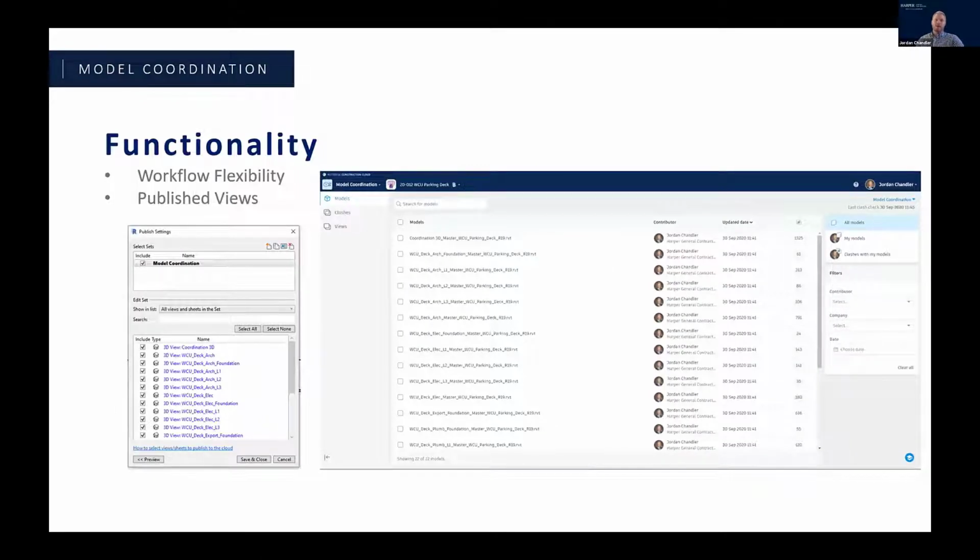Speaking to that, basically from a Revit perspective, I think a lot of coordination in some way or another comes back to Revit and some other file types. But another place where a lot of people get hung up is how do you get the data from Revit to model coordination? You can do a deep dive on that between the plans folder and the project files folder and how those interact with Revit models. But recently, Autodesk gave the ability to set up that coordination space now in both the project files folder and the plans folder, or either one, it doesn't matter. And so that added to the flexibility of the workflows.